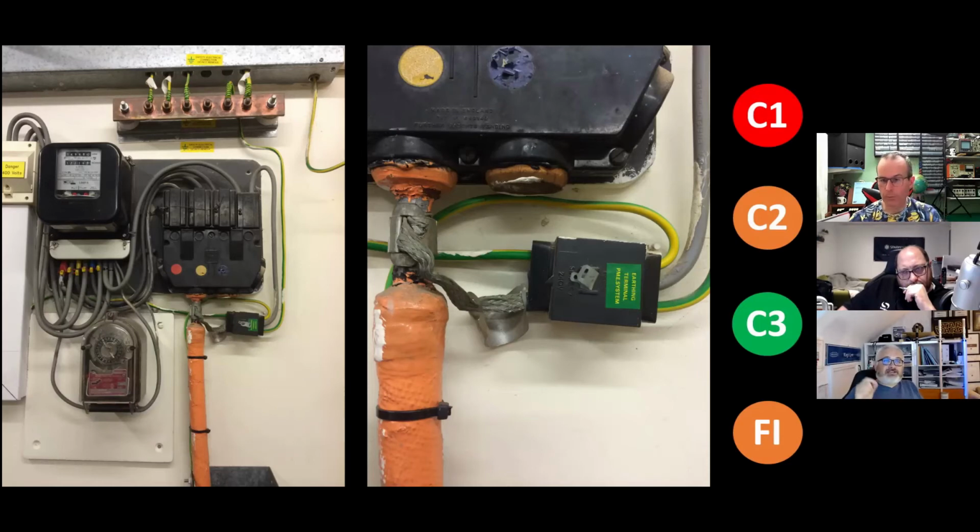Simply providing a separate neutral earth connection to the combined neutral earth cable will not necessarily avoid the hazards of a PME network constructed using combined neutral and earth cables for these types of installation in the event there is a break in the neutral conductor upstream of the connection. Link them.